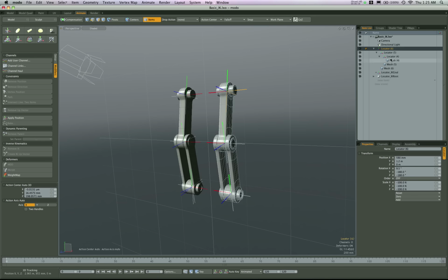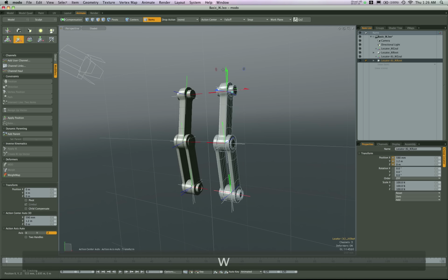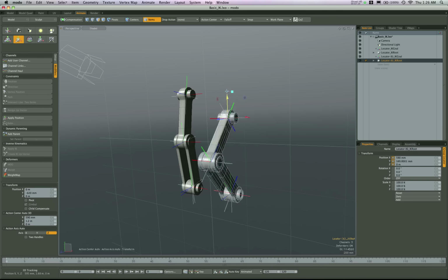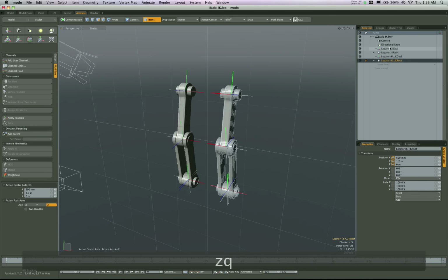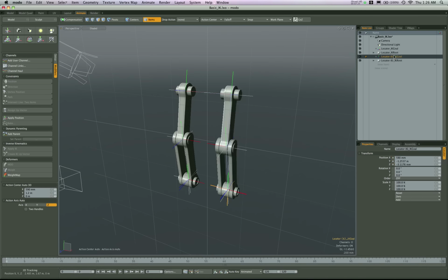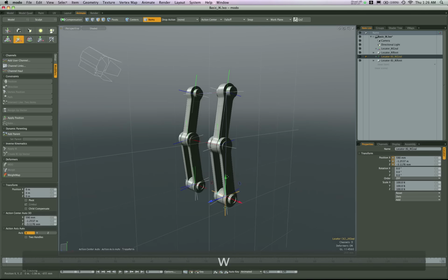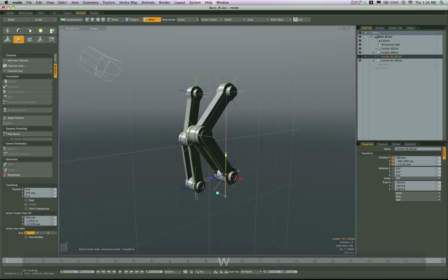So I'm going to do the same thing over here really quickly, so we'll have 2 sets of these. So I'll click those, Apply IK, and I'm going to drag this locator goal up on top of that root just so that they're a little bit more organized here. Now the locator root, if I grab this and move it, will move the top of the leg. Not the kind of thing we're typically going to want to move around all by itself, so I'm going to leave that alone.